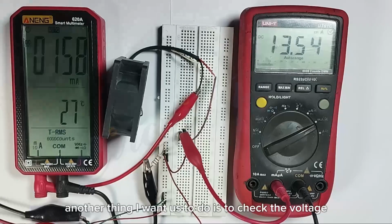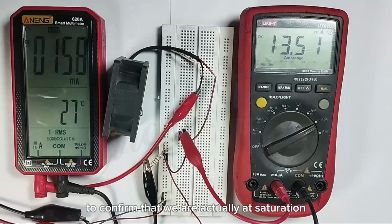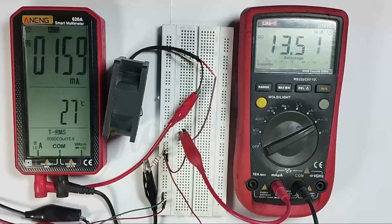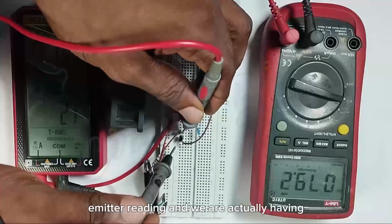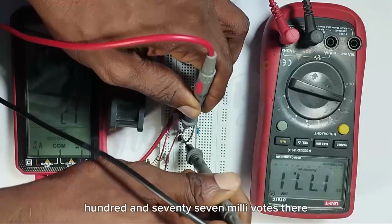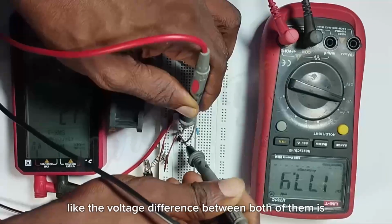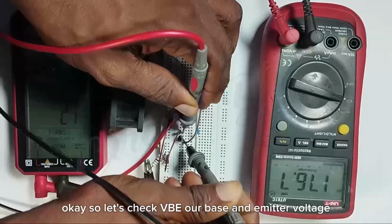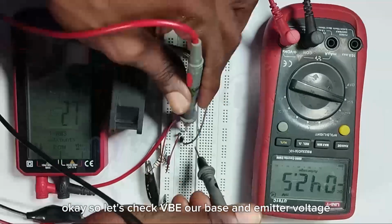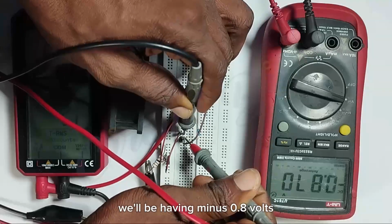So, another thing I want us to do is to check the voltage across the collector and the emitter to confirm that we are actually at saturation. So, we take the collector emitter reading and we are actually having 177 millivolts there. The voltage difference between both of them is very little, so we see we are at saturation. Okay, so let's check the base and emitter voltage. We'll be having minus 0.8 volts.